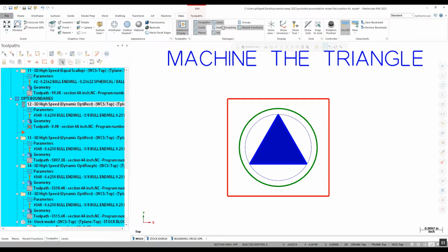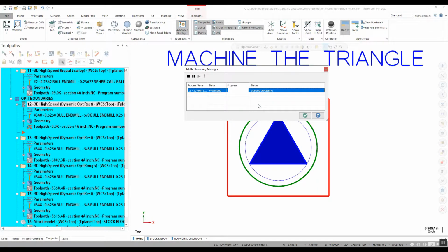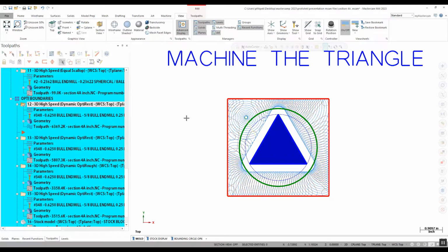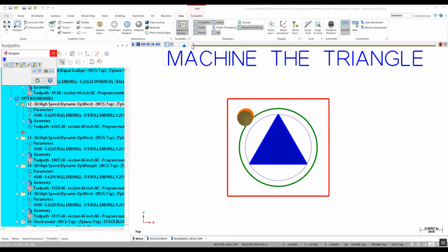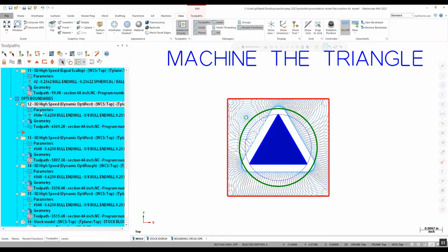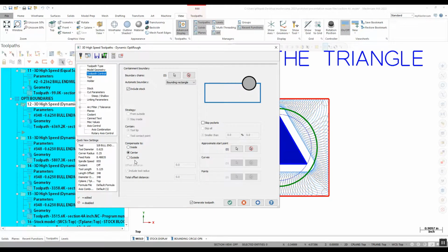And she's crunching along here. Now, as far as these options go, do you have to use the new options? No. Potentially, maybe they will help you in some situations. So here's the cut. And it's going to be an inside strategy once again because I'm looking at a stock model, looking at the stock page. And now you'll see that I stayed inside. I cut to the center. Once again, if I wanted to get to the outside, I'd still have my same controls here: inside, center, outside.